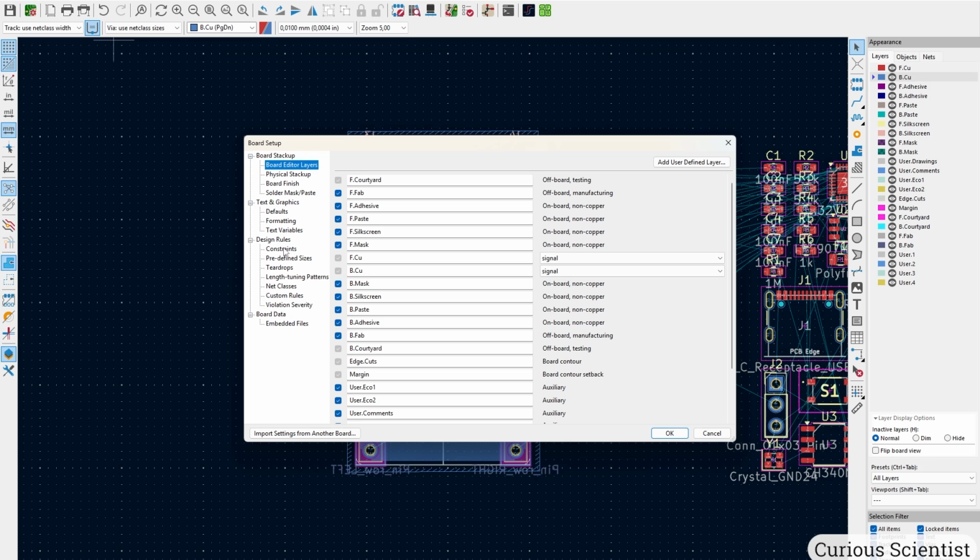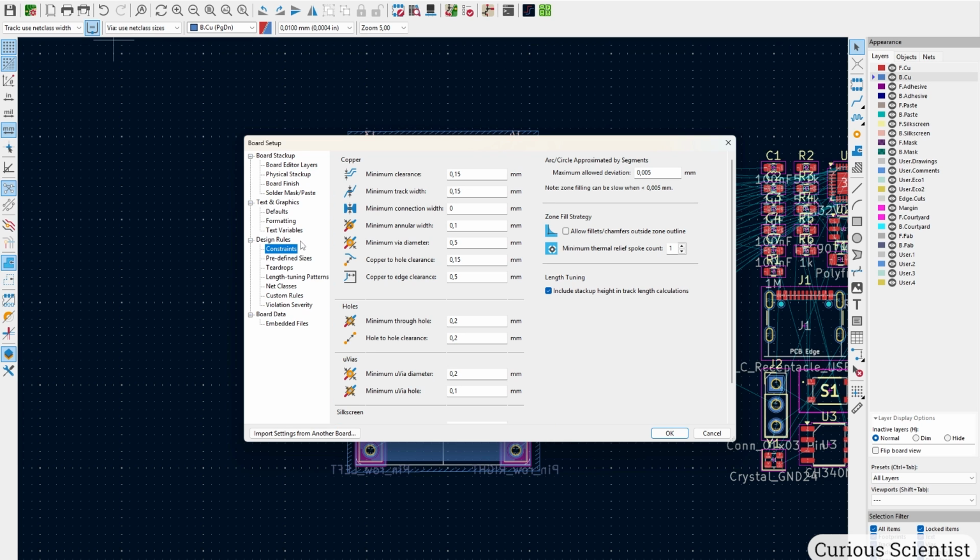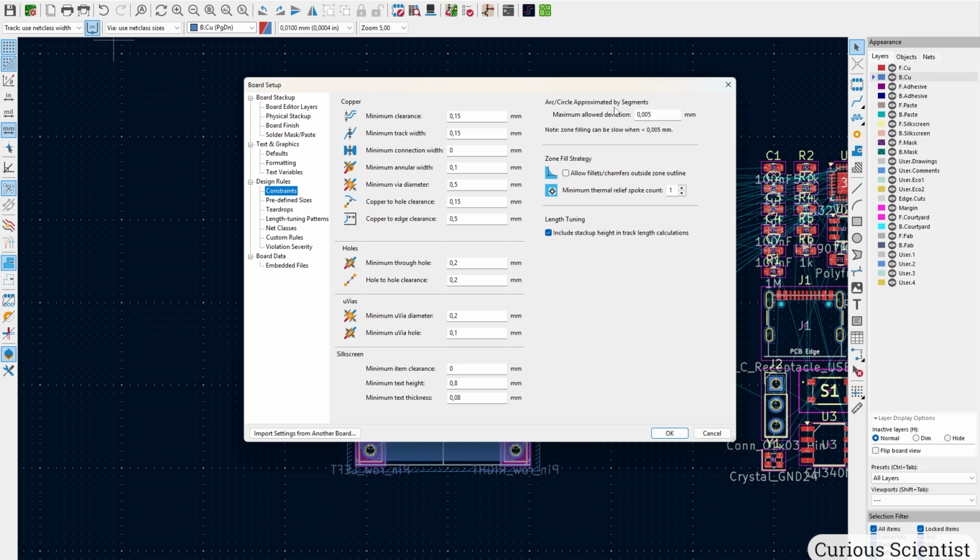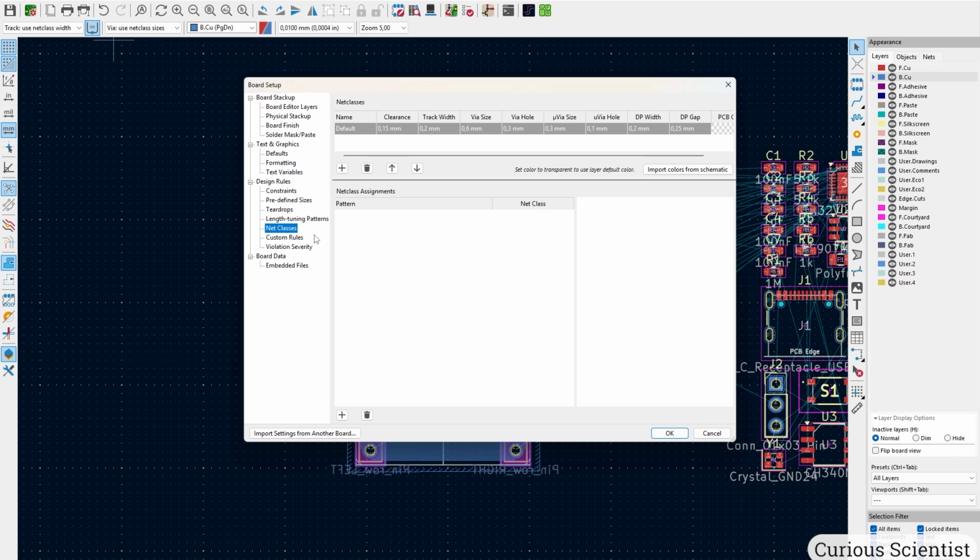And I want to show you that we can check a few design rules. So if you want to exactly duplicate this board or this kind of, let's say, design principles, then this is the clearances and tolerances that I'm using here. This is still producible by PCBWay, and it will not increase the price. Sometimes if you have funny tolerances or funny requirements or too tight requirements, then it can be that certain colors cannot be produced, or you will have to pay a higher price, but this board will be still within the cheap pricing.